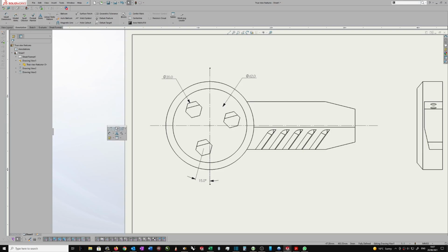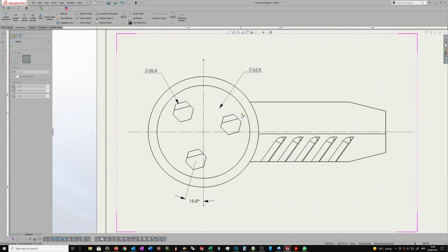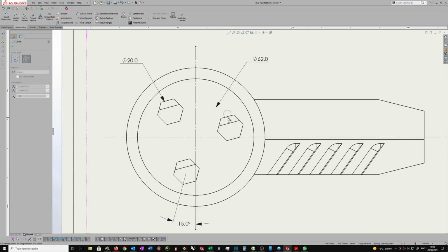So I'm going to select my circle command, but instead of selecting the center circle, go to the perimeter circle and simply select 3 perimeter lines. And you can see the little tangent sign is popping up. So it will snap to tangent. You just have to be patient to wait for that symbol to appear. So that's those 3. There we go.